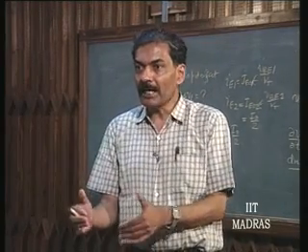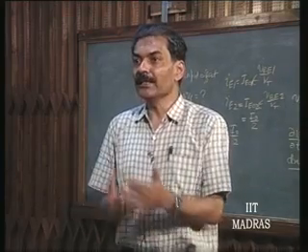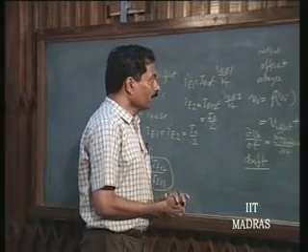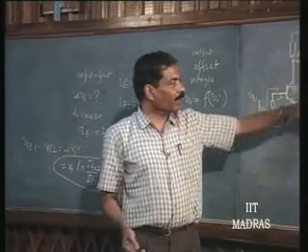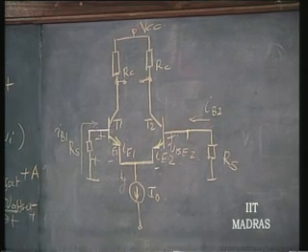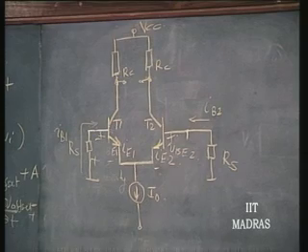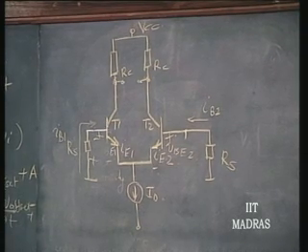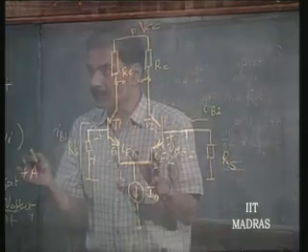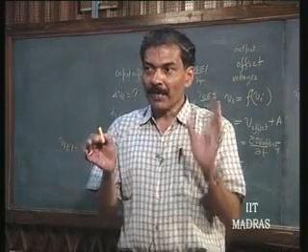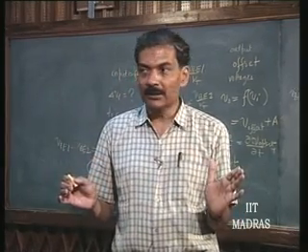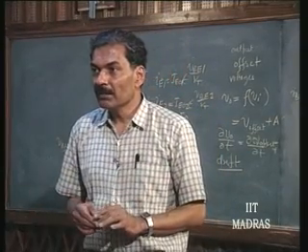In worst case situations, you have to add these voltages always. One way to tackle this in a very crude manner is to always connect from the input to ground or virtual ground an effective DC resistance equal to the source resistance, if it is not a feedback stage. Otherwise, the principle is from plus and minus both terminals to ground, you must connect equal valued DC resistances to account for bias current offset.